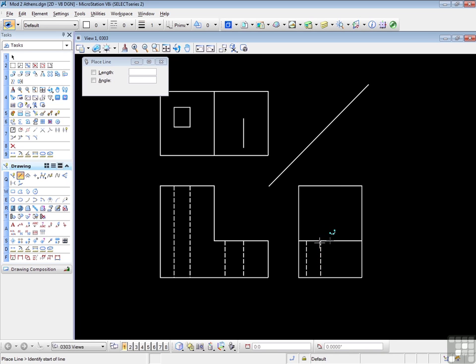Back to this one. Find the snap point, F11, O key, up, enter N, there, O key, come across, and just enter. Nearest is already on, which is just fine. There's my snap point. I snap, and I carry across here, and I hit enter, and I pick up that. Now notice that the nearest is gone.